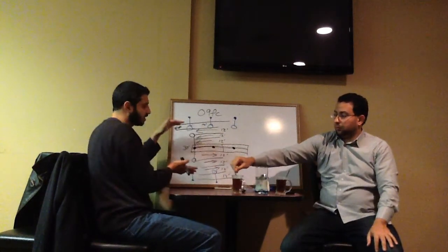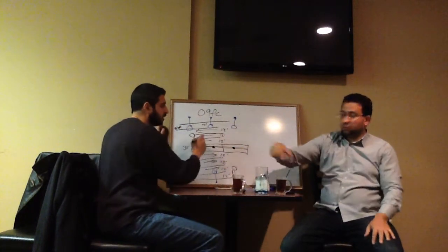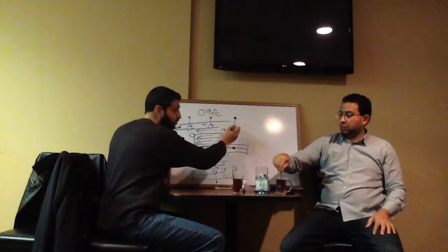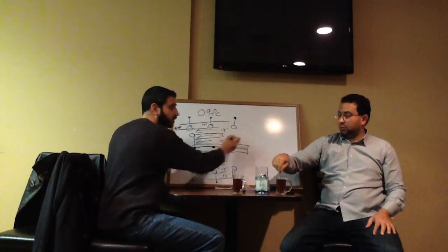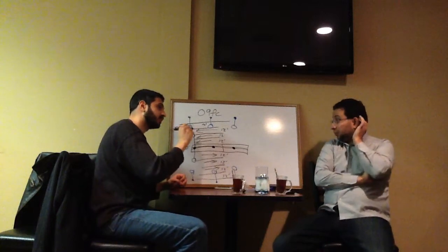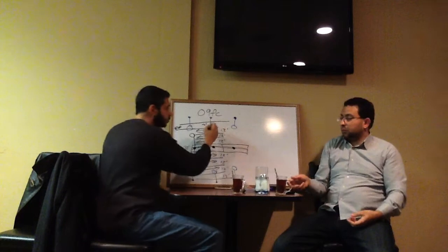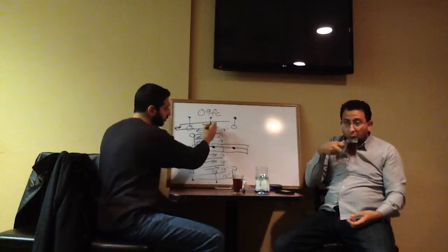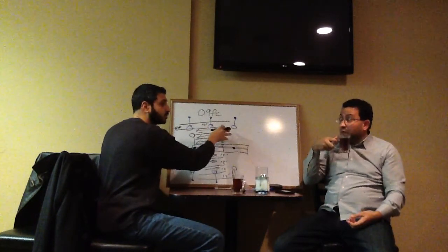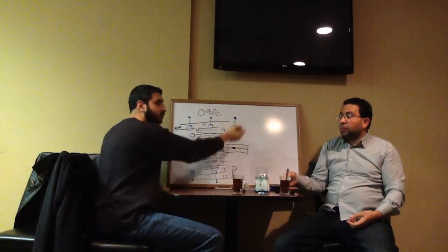And it's 36 feet for a mile long. You don't have to calculate the whole area. What you do is you pick 2 poles in the center, and that will be your calculation grid, because it has to calculate each point separately. So it's going to take a long time if you have 1,000 or 1,000,000 points. So what we do is we calculate between 2 poles, and that's the typical analysis. If you calculate it here or here, it's going to be the same thing because it's repetition.